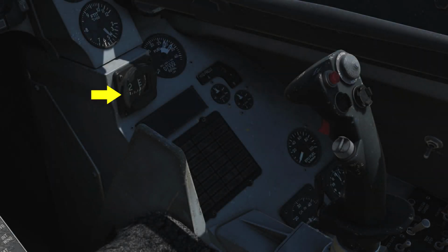Moving down to the right is the right auxiliary panel. The magnetic compass is a self-contained indicator which shows the heading of the aircraft in relation to magnetic north. The fuel gauge displays total remaining fuel in the digital window in pounds of fuel, and the 2 needles indicate fuel in the aft and left, and forward and right. If the 2 needles become too divergent, indicating a fuel imbalance, then red will be showed at the base of one of the needles. In such a case, you would then use the engine feed switch on the fuel panel to correct the imbalance using the aft and forward settings.